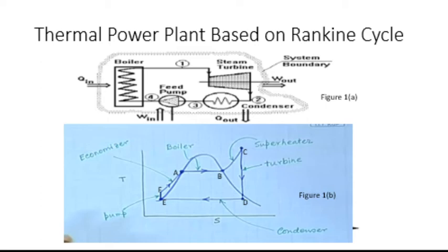After the boiler, where will the steam go? The steam has to go to the turbine, but before that, you should know that in between the boiler and the turbine there will be a superheater, because you have already completed thermal power generation. Why will the superheater be there? Because if you heat the fluid only to the boiling point, as soon as the fluid comes out of the boiler and enters the turbine, the temperature will suddenly drop and it will be converted into liquid again.